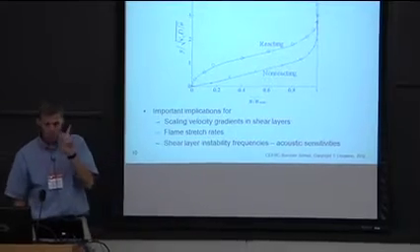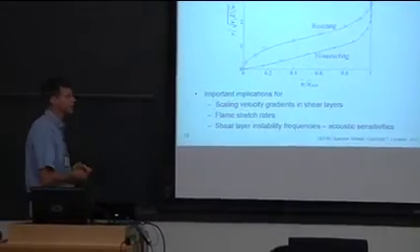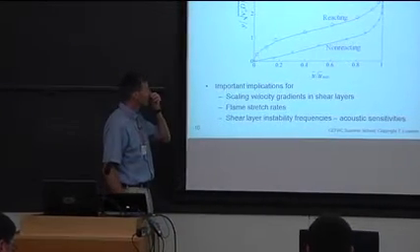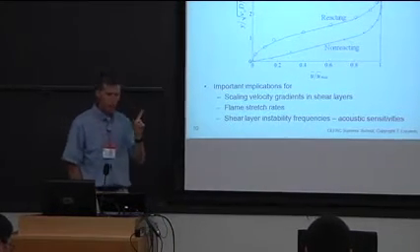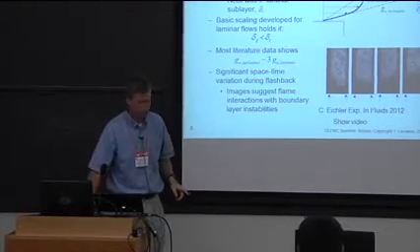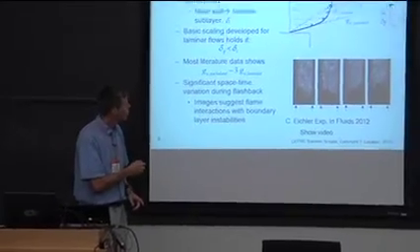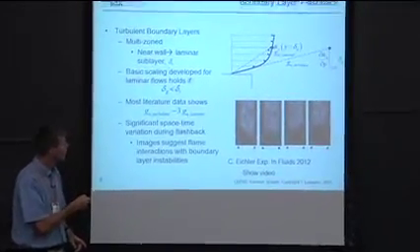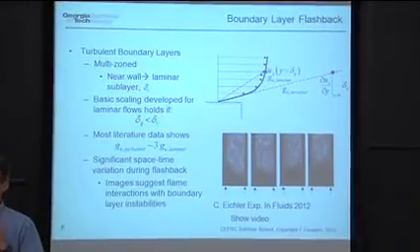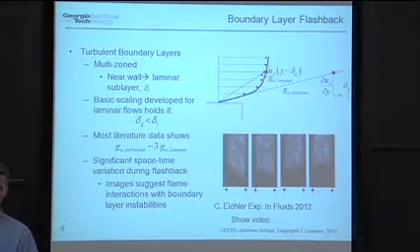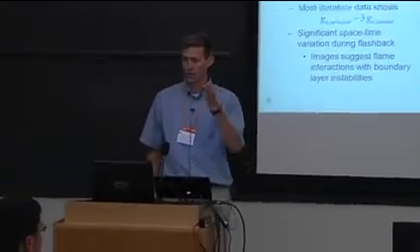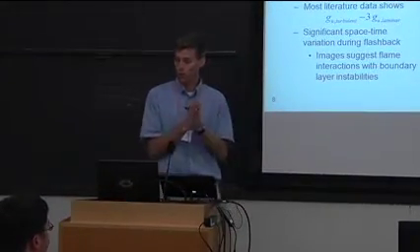So one other important effect which I want to emphasize here is heat conduction and influences on boundary layers. What I have here is a plot. This goes back to the point of what the flow velocity profile looks like, to understand flashback. And I want to emphasize that only in the zero heat release limit, which isn't a very interesting limit for combustion, can you prescribe the flow velocity. Otherwise, it's part of the problem.